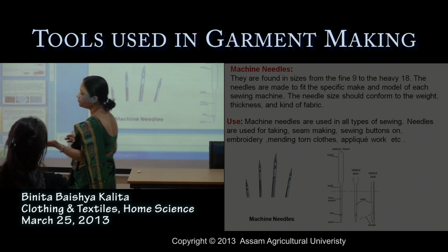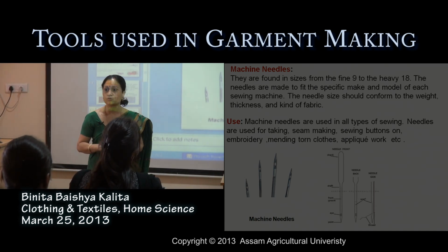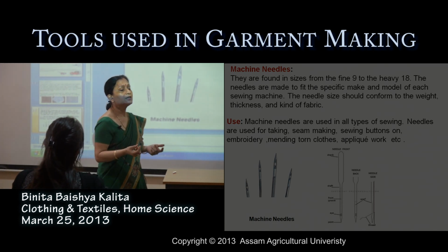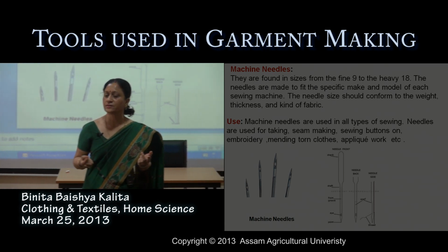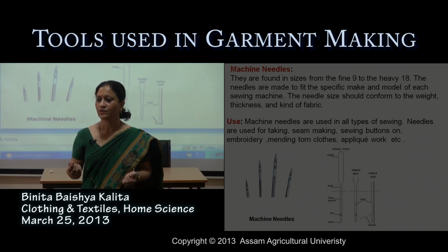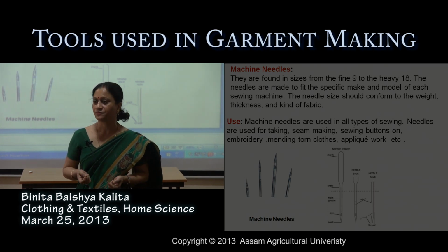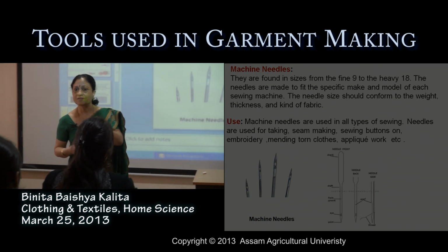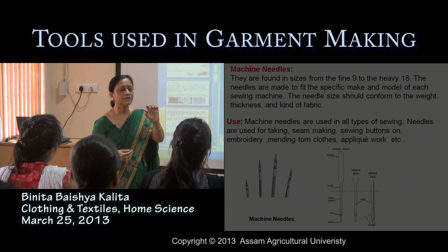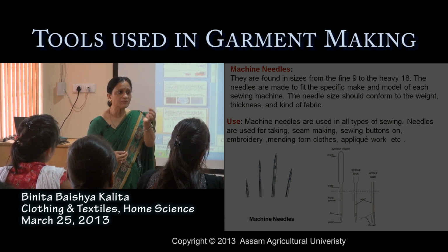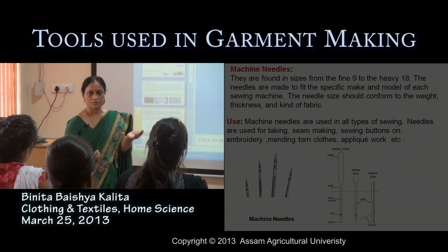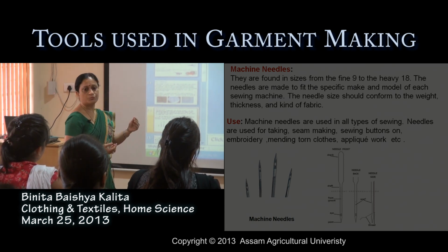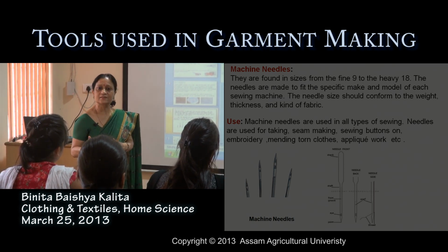Okay, if you want to stitch a trouser made of jeans material, in that case, what type of needle do you have to use? Finer, medium, or heavy? You have to use the heavy needle, is it not? To withstand that, because the material is very thick. If you use the finer needle, the needle will break down. So you have to use a thicker needle, which can help in the progress of your work, so you can easily stitch the garment.